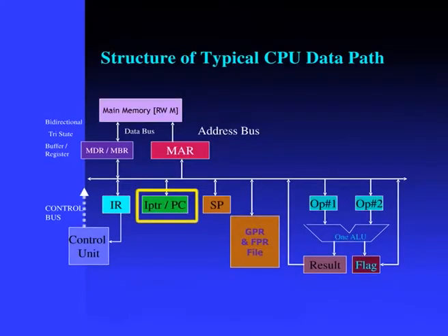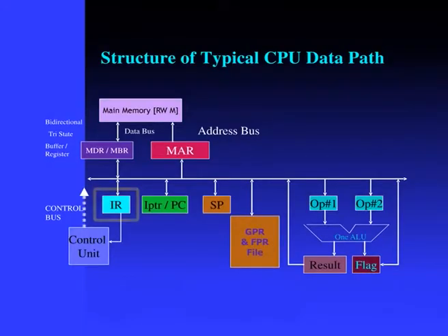The program counter register keeps track of the execution of the program and holds the address of the next instruction to be fetched from memory. We can also say that logically the program counter points to the next instruction to be executed. The instruction register holds the instruction currently under execution. Its output is given to the control circuit, which generates the timing signals that control the various processing units involved in the execution of the program.